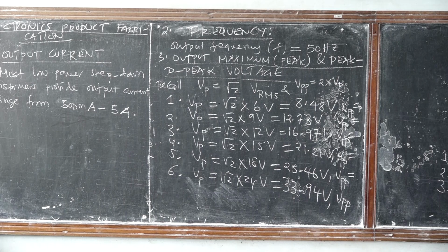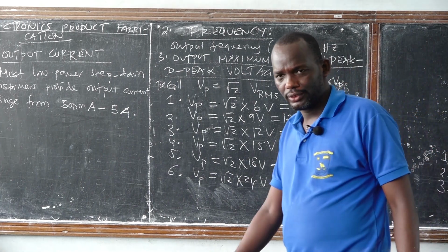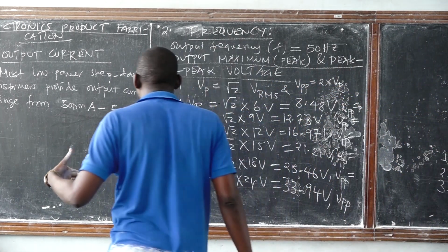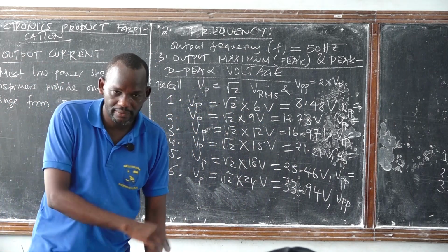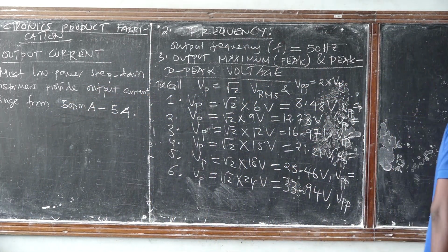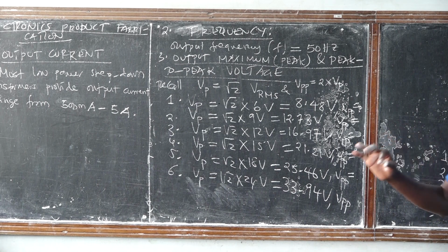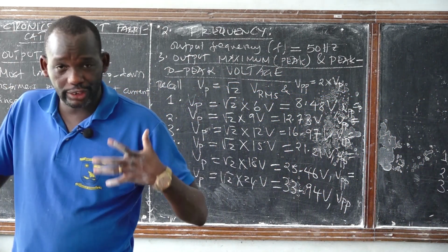If your entire system needs a total current of 1 ampere, and you have designed your linear power supply using a transformer of 5 ampere, while your system just needs to draw 1 ampere, in that case your linear power supply will work and power your circuit safely, because it can provide the amount of current required by your system.